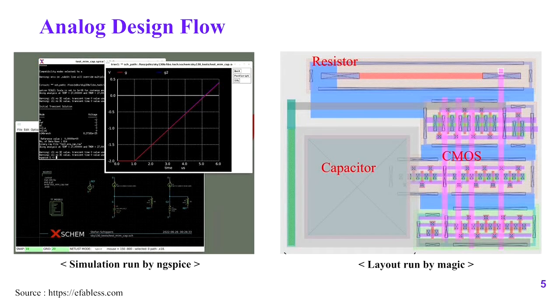But among the RF circuit components, one essential component is the inductor, right? The issue we had is that the Skywater PDK doesn't have an inductor model. Although they provide one inductor model, it's closer to just an ideal inductor.